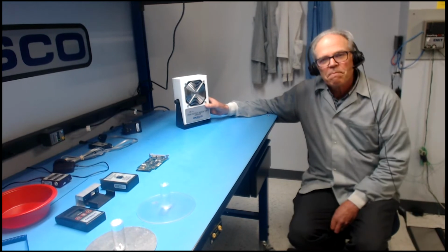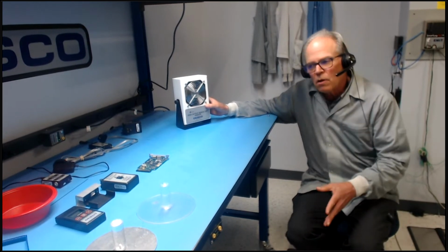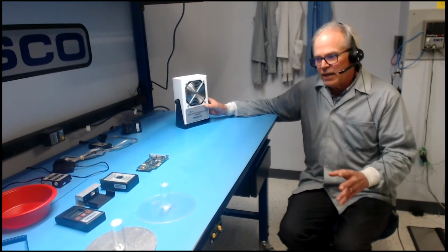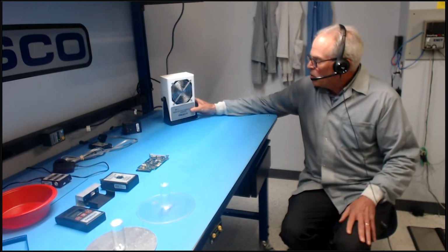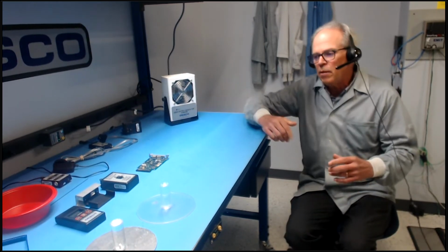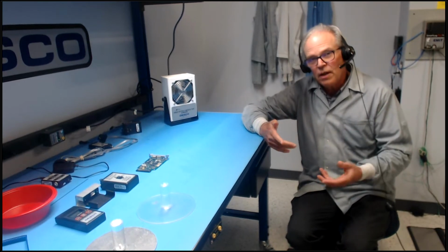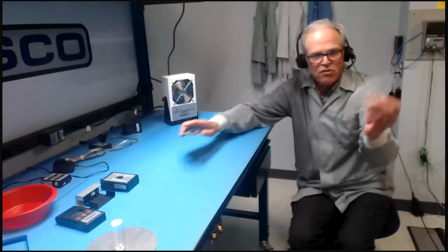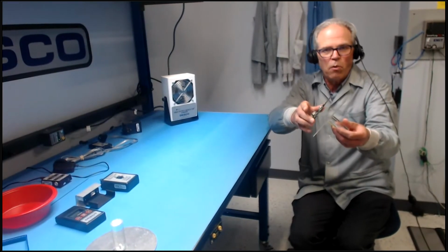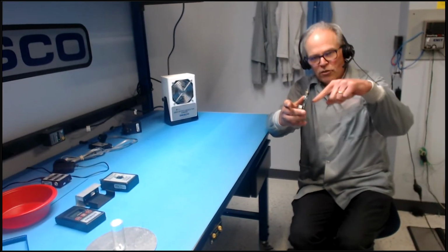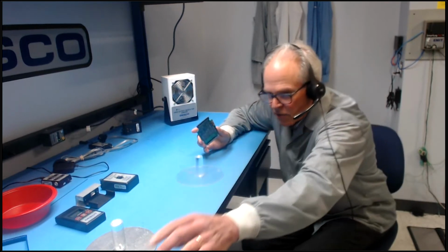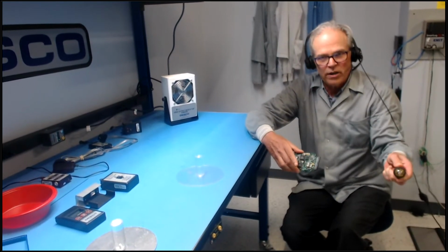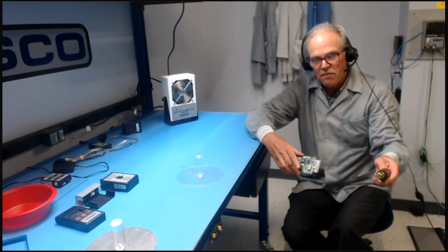Let's talk about the user-defined aspect of ionizers. The problem an ionizer prevents is from an insulator. Here's a plastic paddle being too near this board. Charge goes onto the board, and then if I touch it with a hand tool or something metal, it's going to discharge, and that's a charge device model event.